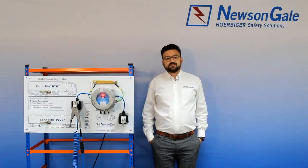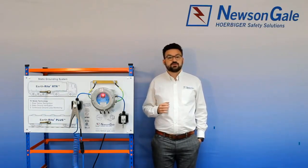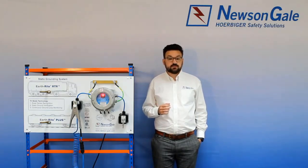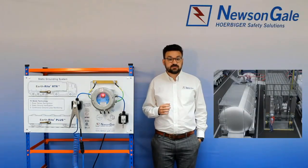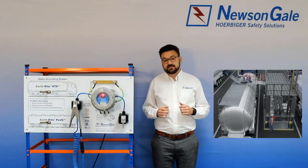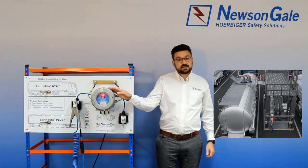The potential risk of static charge accumulation on road tankers and tank trucks can be managed through the correct installation and proper use of the Earth-Rite road tanker recognition system from Newson Gale, ensuring suitable grounding and preventing operation of equipment in unsafe conditions. In this video, we're going to explore the principles of operation of the RTR system, and although predominantly the same as Newson Gale's MGV system, the RTR is gantry mounted rather than a vehicle installed system.